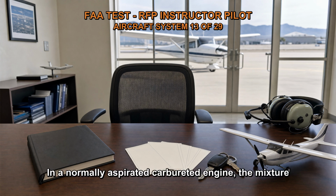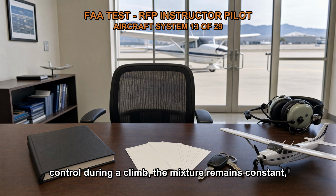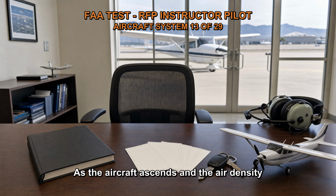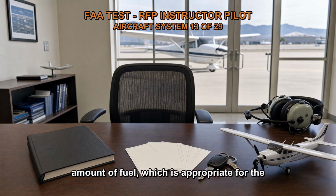In a normally aspirated carbureted engine, the mixture control determines the ratio of fuel to air for proper combustion. If no leaning is made with the mixture control during a climb, the mixture remains constant, assuming a fixed setting. As the aircraft ascends and the air density decreases, the carburetor continues to deliver the same amount of fuel, which is appropriate for the denser air at lower altitudes.